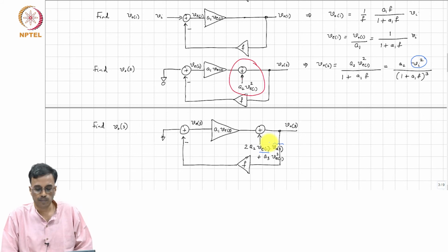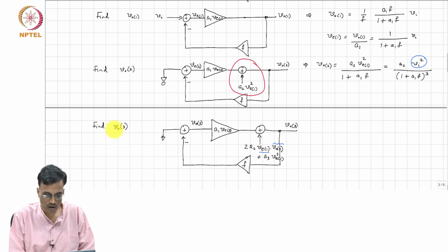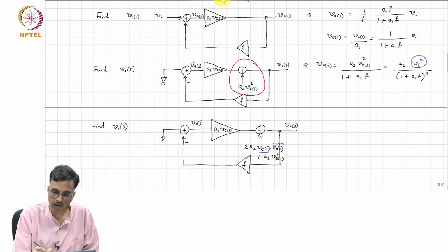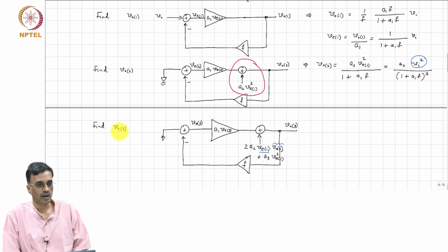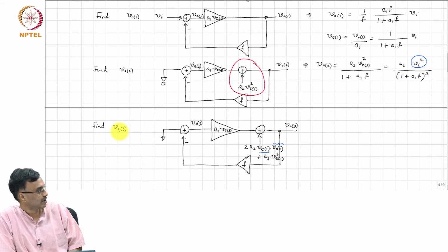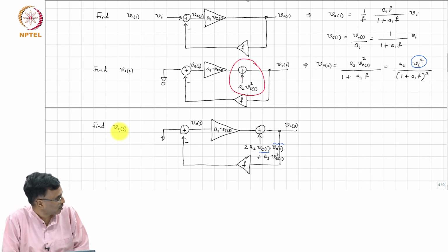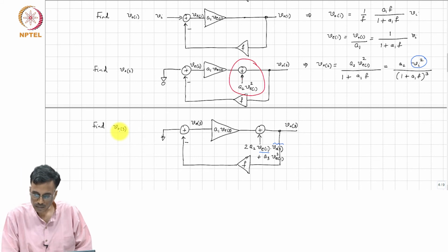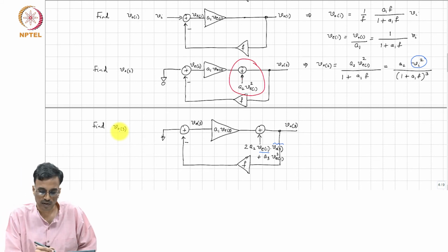Whenever you are in doubt, to find the third order response, you want to make sure that if you double the input, the second order response must go as 4, and the third order response must go as 8. So, what do we see here now?